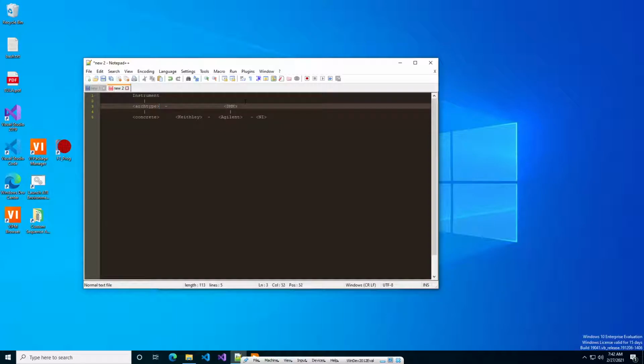Depending on which toolchain you're using for your intermediate archetype instruments, you don't have to put any logic that actually works in there. You could define just the API, or you could define a default API that should work in most cases. For instance, if you're used to using mostly SCPI instruments, you could implement the SCPI commands at the archetype level.